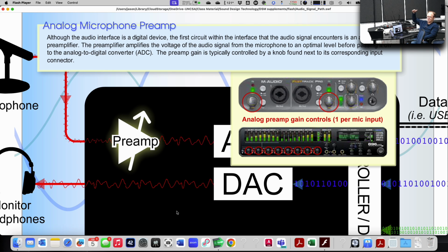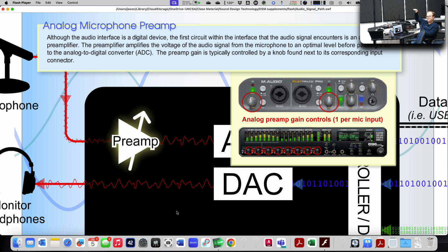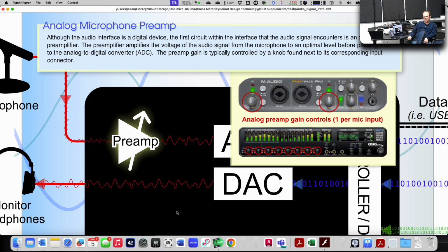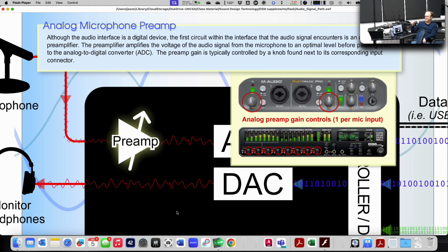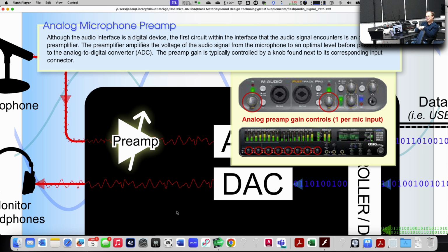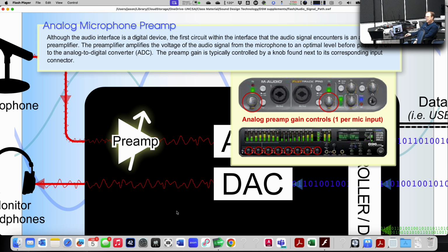If you got your gain structure really good and you're feeding your stuff in really hot, you can have a noisy preamp and you might not notice it because there's such a big difference between its noise and your signal. But if you aren't sure, and you're going to be recording really quiet things and you're not necessarily going to get the gain just right, your signal might be really close to that noise. So it just depends. But generally speaking, you get what you pay for there. Okay.